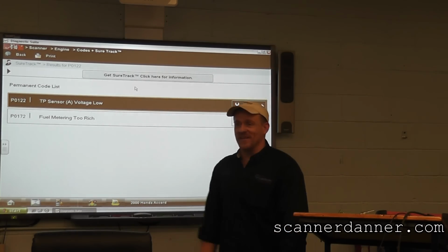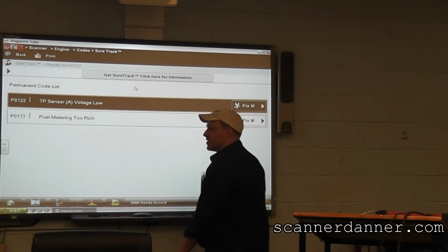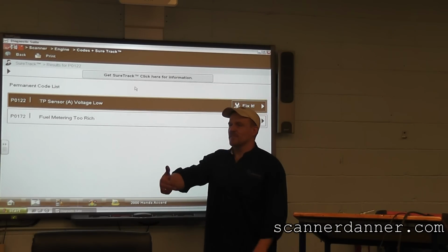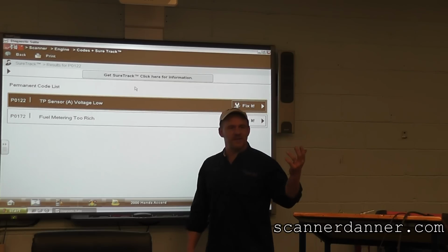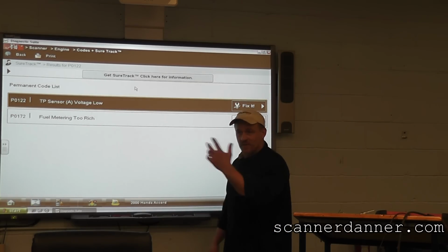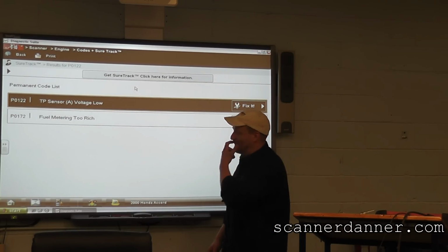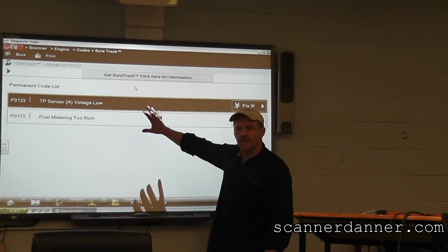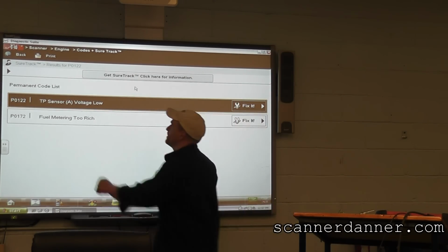Who knows? Just my guess. Yeah, no, it's a valid guess. But remember, TPS was plugged into where the MAP was plugged into the TPS, so our load calculations were way off, and under that scenario, yeah. All right, we can wipe these out, would you agree? These aren't coming back. That's why that light's on. We'll do that.